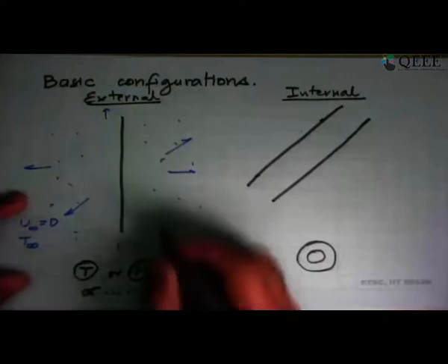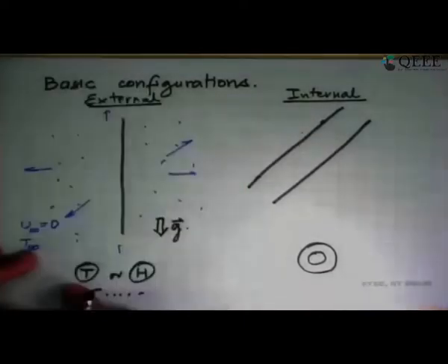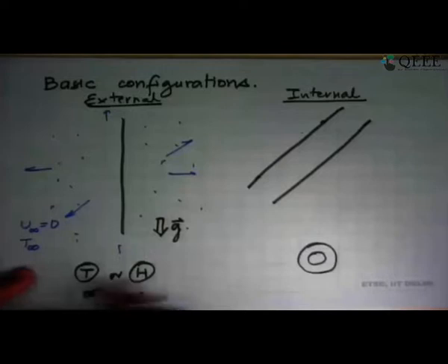This is in an ambient fluid where the walls are very far away, and it cools by natural convection. An essential feature here is that gravity is an important player, so g you must show there. The plate could either be isothermal, heated or cooled, or isoheat flux, or any other combination.